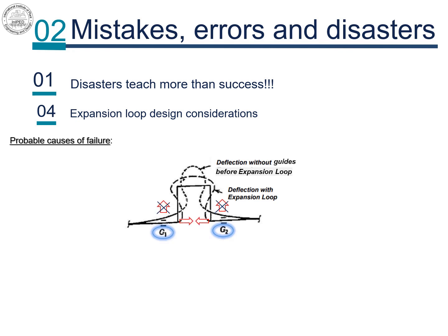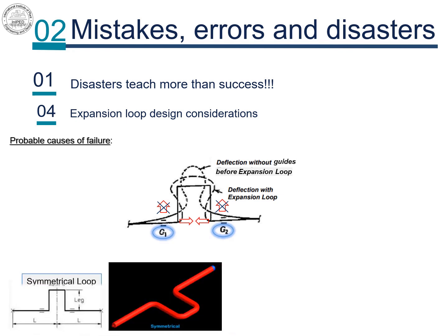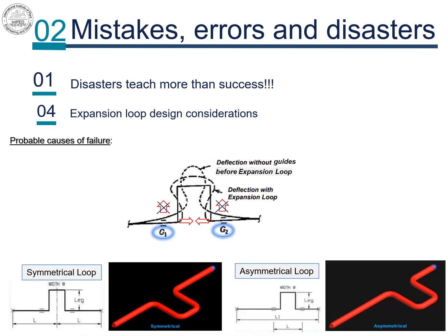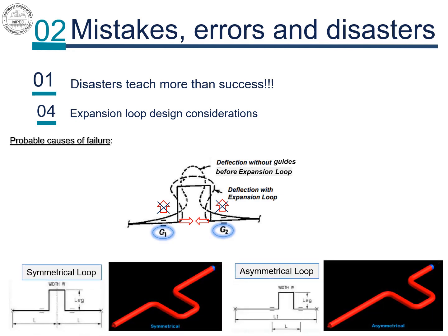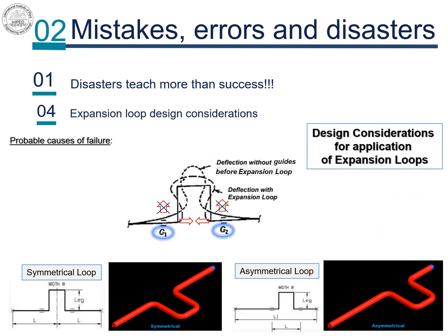The thermal expansion loops can be symmetrical or asymmetrical, in terms of their position in between the anchors or fixed supports. Also, the important question that may have not been considered is, when does the expansion loop become too large, so that the line needs multiple expansion loops instead of one? More than one loop may be essential when the forces required to bend the loop are too great and the anchors cannot be economically reinforced. Anchor forces become too unbalanced and steel cannot be economically braced.